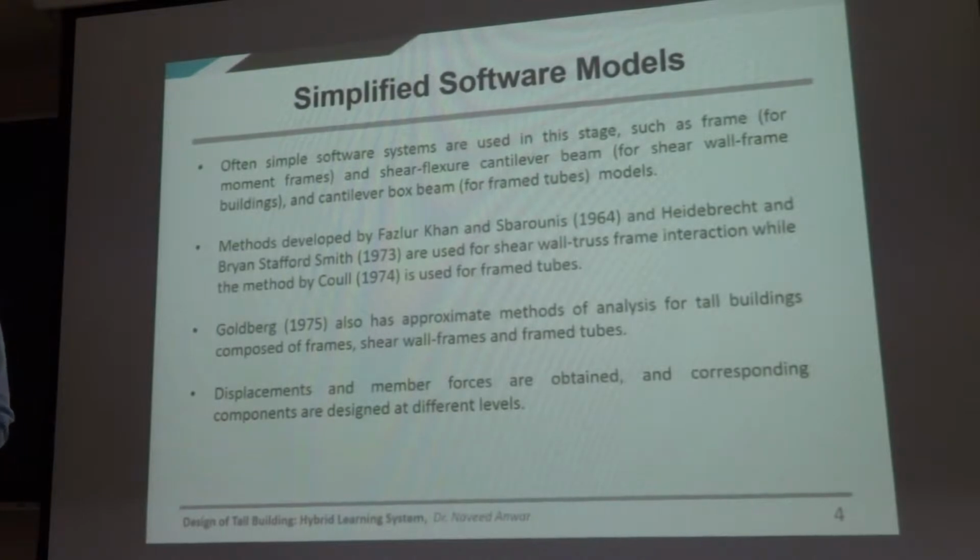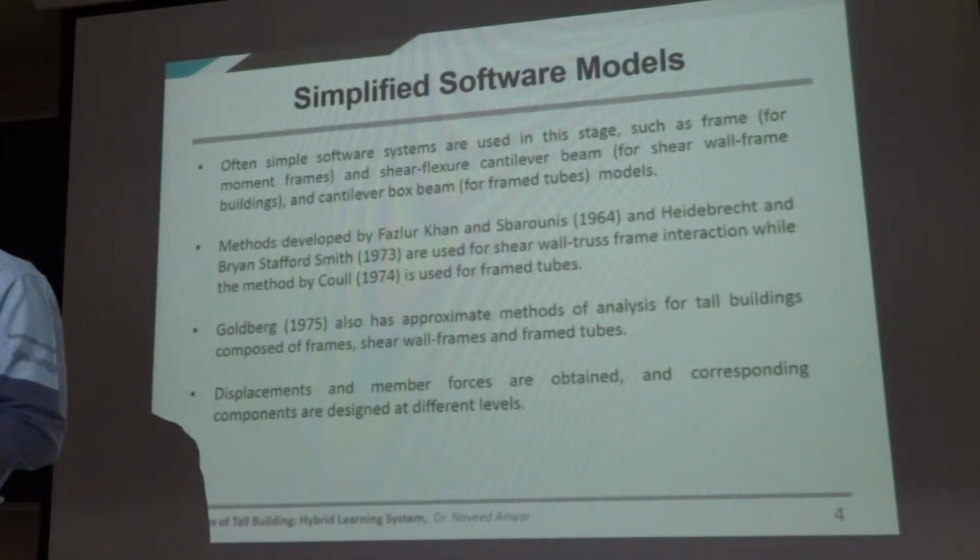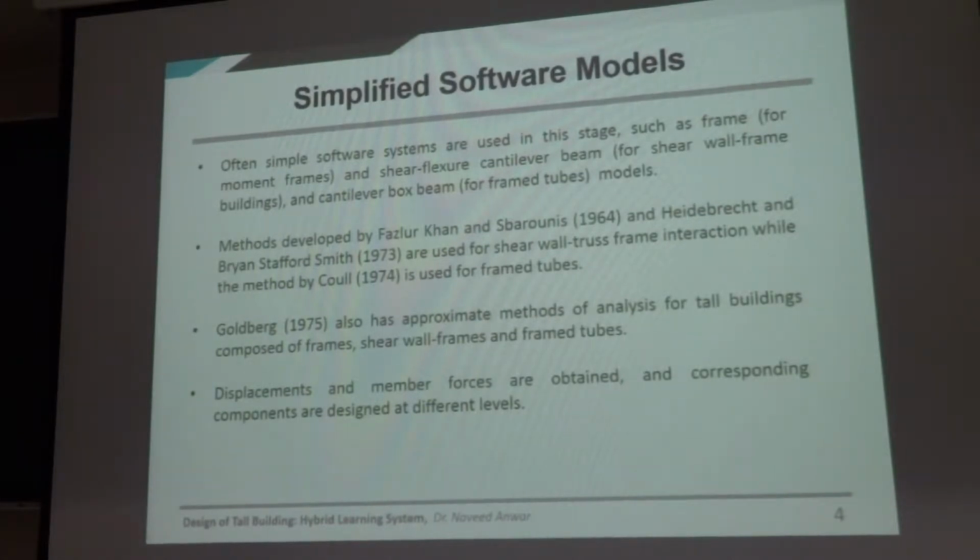But it's a very important decision because the weight of the building will depend on what system you select. And weight of the building will govern the load on the column, load on the foundation, load on the shear walls, and will also govern the base shear, mode shapes, everything, mass. So mass is very important.